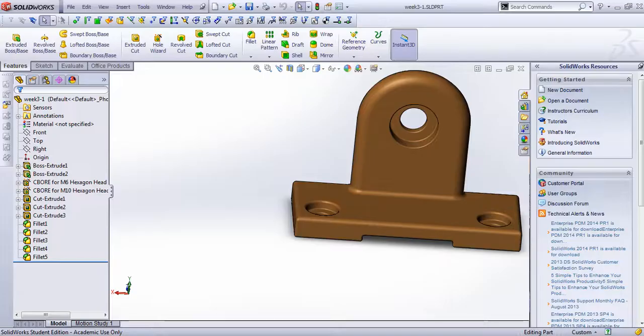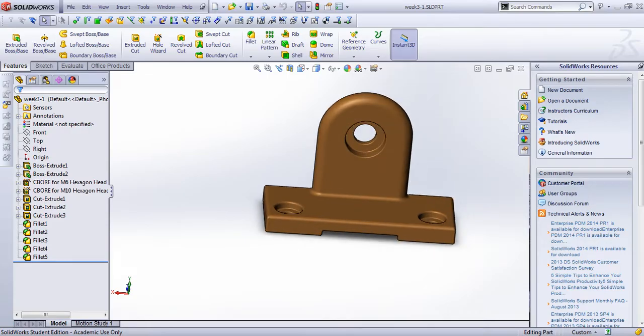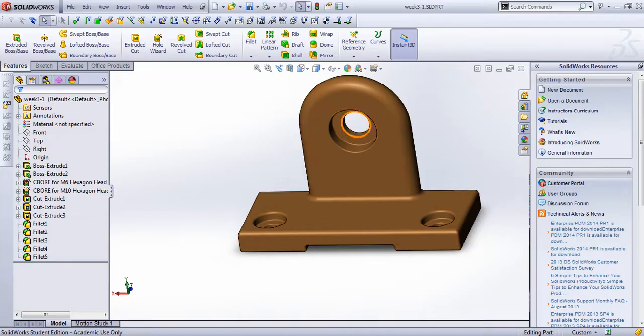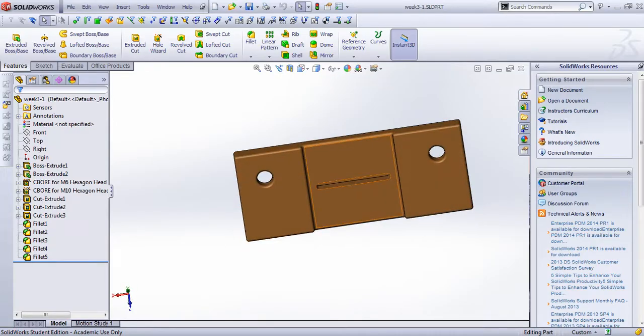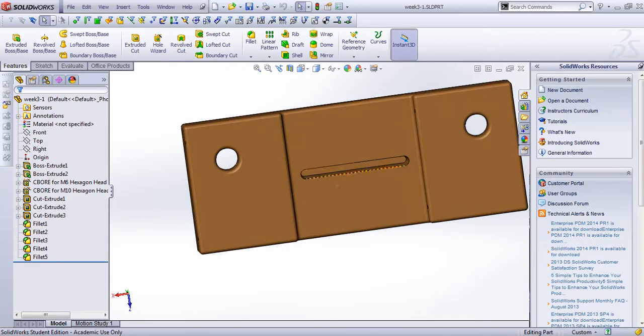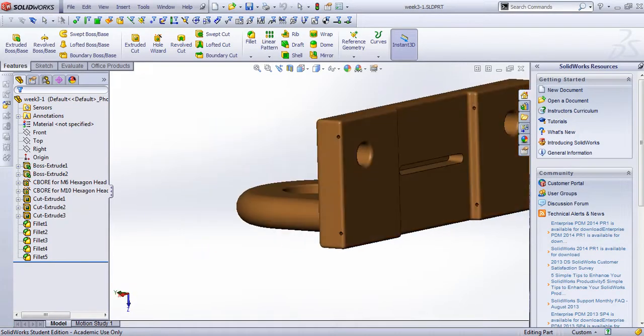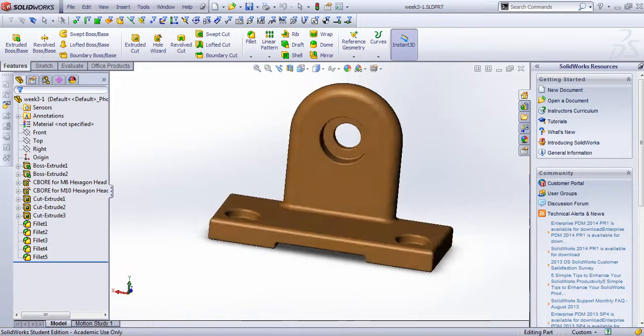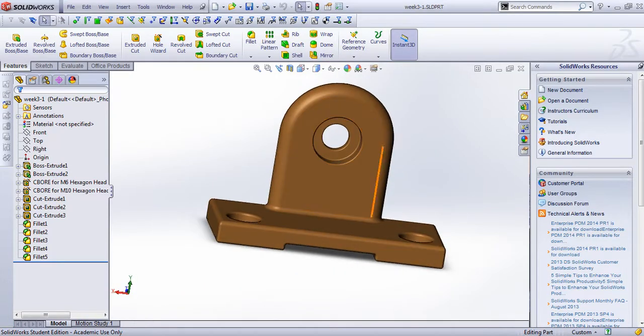In this screencast, we talk about the drawing sheets, orthographic views, and how we actually edit and set up our drawing sheets. If you recall, previously we made a simple geometry, a bracket with three holes, and then we have here the slot, and then we got the keyway with set screws on both sides. So this is 3D modeling. We mentioned that in engineering this is very important. We do have also orthographic views of this created model.